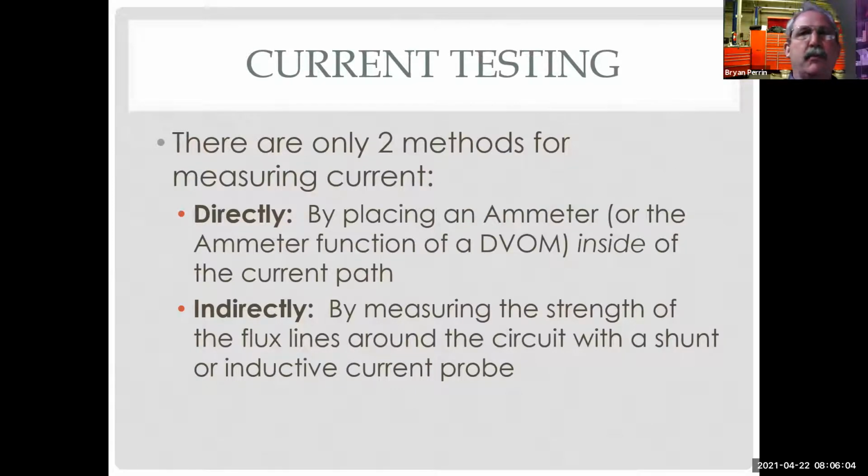And then we have a milliamp probe. A milliamp probe is designed to measure current flow really under an amp. So it's very, very sensitive. It doesn't have a lot of range. It's only going to read a couple of amps max. Very sensitive, and they're fairly expensive. So I actually don't own a milliamp probe because the price hasn't dropped on them yet. And I just refuse to spend $500 for one, especially since I'm not in the shop anymore.